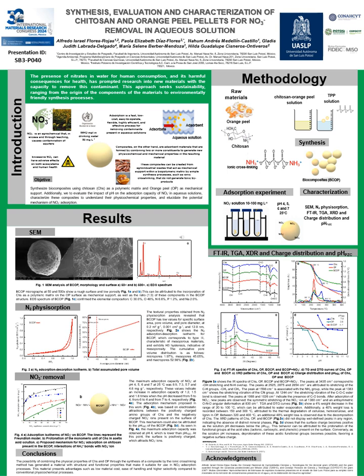The World Health Organization sets the maximum permissible limit of nitrate in drinking water at 50 mg per liter, equivalent to 11 mg per liter of nitrate as nitrogen, using a conversion factor of 0.226. Nitrate can be removed from water using treatment methods such as ion exchange, electrodialysis, reverse osmosis, and adsorption.